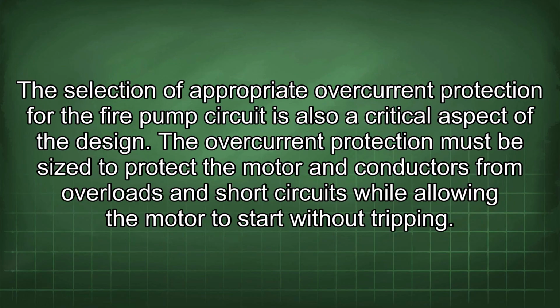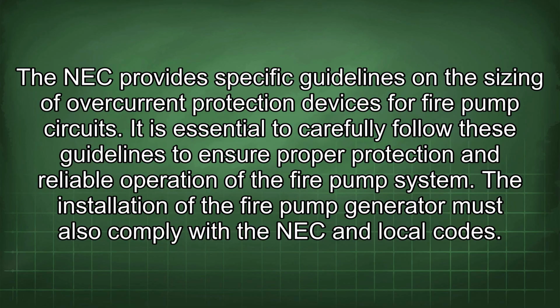The selection of appropriate overcurrent protection for the fire pump circuit is also a critical aspect of the design. The overcurrent protection must be sized to protect the motor and conductors from overloads and short circuits while allowing the motor to start without tripping. The NEC provides specific guidelines on the sizing of overcurrent protection devices for fire pump circuits. It is essential to carefully follow these guidelines to ensure proper protection and reliable operation of the fire pump system.